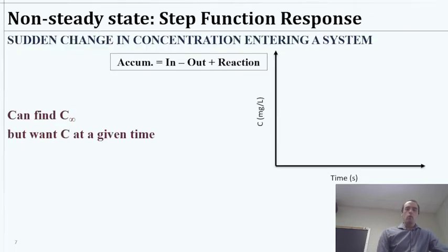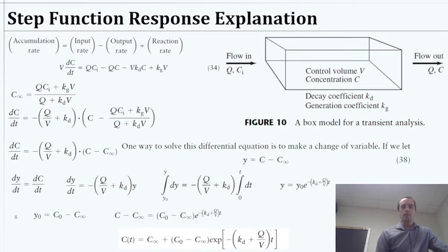Okay, so what they're saying is, for this system, we have accumulation rate, V dC/dt, is equal to the inputs minus the outputs, QC initial minus QC. Then they have the minus first order decay, so that's C to the 1 power, plus the 0 order growth, that's C to the 0 power. So all of that is in there, just as we would expect.